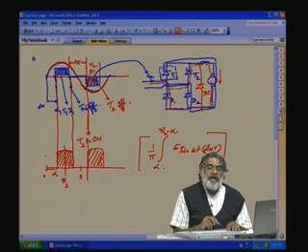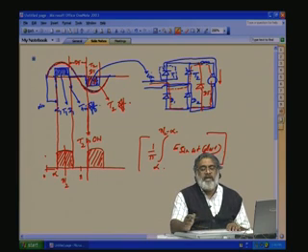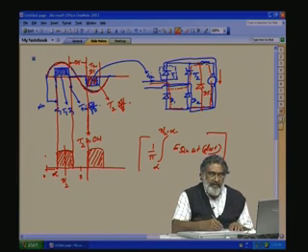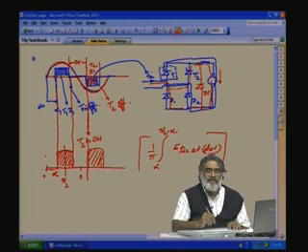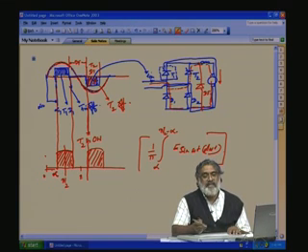Okay. Now, we have 2 degrees of freedom. Previously, in all the phase angle control we had only 1 degree of freedom, and we can only control the start of the firing angle, that is alpha, the start of turning on the devices. But switch off happens whenever the other thyristor is symmetrically fired, during the negative portion of the voltage waveform, again same alpha starting from the 0 crossing, we have to fire the next thyristor. That type of commutation is called natural commutation, but here we are doing forced commutation, and we require one extra diode here, but power factor improvement is there.